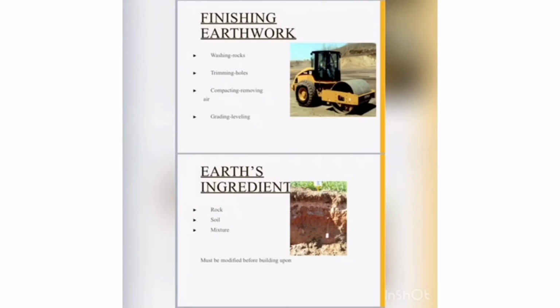Fourth, grading, leveling. Grading is an important step that is carried out prior to construction that helps to prevent water from flowing towards the foundations of a new house. Builders will generally try to create a grade sloping away from the foundations of the house, though this can be difficult if the site is a particularly steep piece of land.